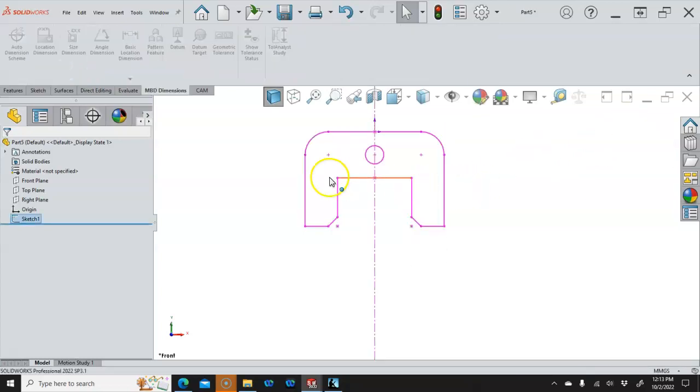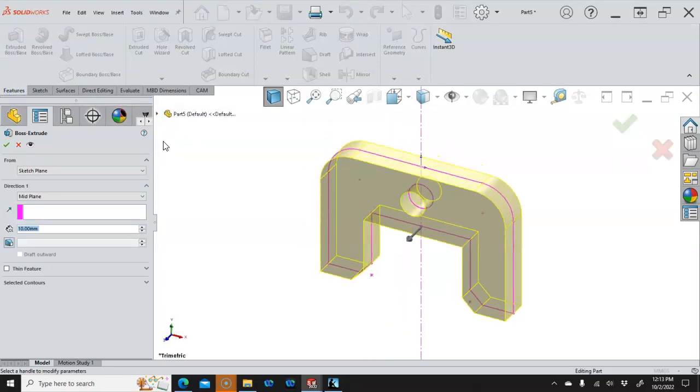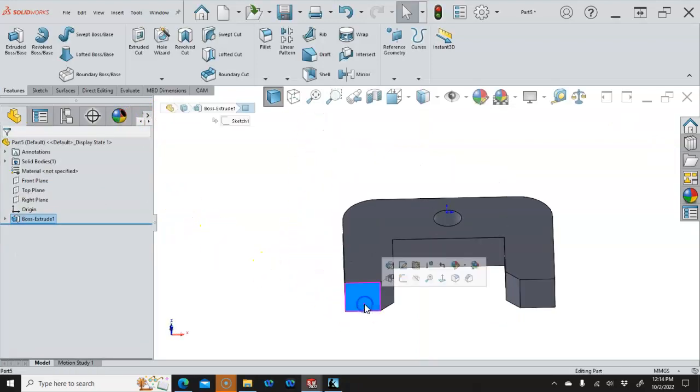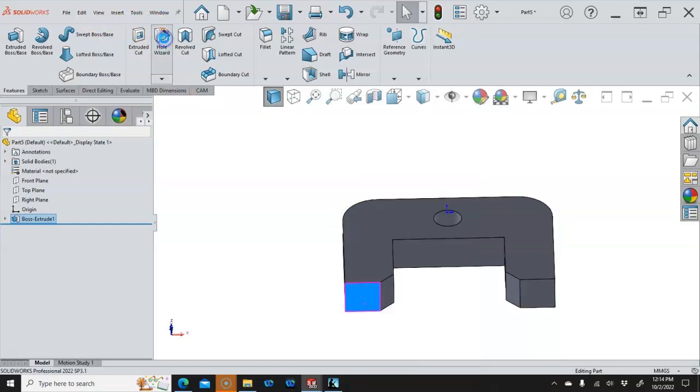And then the feature extrude. Oh yeah, I got out of it, so extrude. And we're going to have 10 millimeters on the thickness. We can stay with midplane. And then our geometry. Let's just go to the hole wizard. See if I could find it.